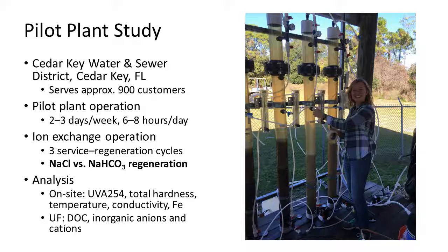And so that has logistics, though, when you're trying to run a pilot study and you need a continuous supply of water. So for that reason, we operate around 2 to 3 days per week, and then try and get in as full of a day of operation as possible. We have a big storage tank I'll show you that allows us to get a full day of operation in, even if the water tower is full. I'll get into some of these details, but the ion exchange operation, we're doing 3 sort of service regeneration cycles per condition. Again, really here focused on the sodium chloride versus sodium bicarbonate. Elise does some analysis on site and then brings samples back to the lab for additional analysis.